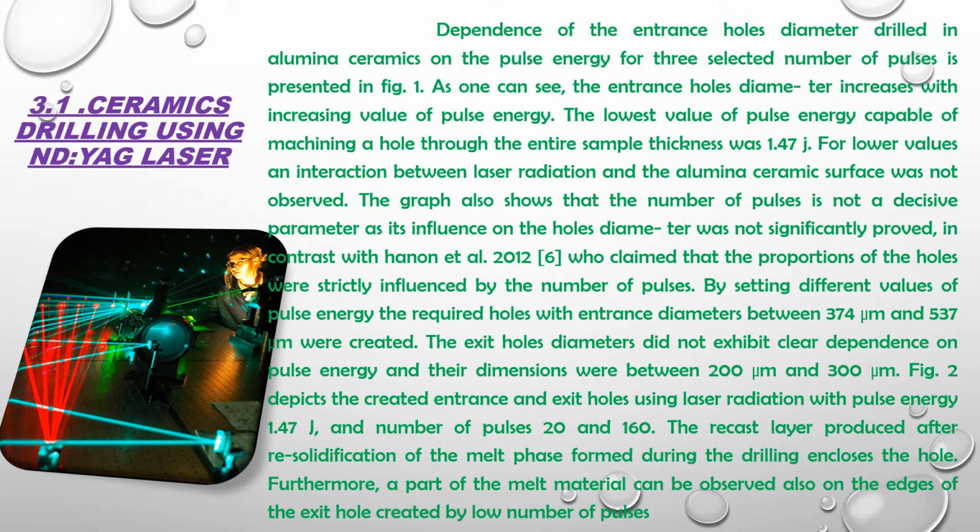Ceramic drilling using Nd-YAG laser. The dependence of the entrance hole diameter drilled in alumina ceramics on the pulse energy for three selected numbers of pulses is presented in figure 1. As one can see, the entrance hole diameter increases with the increasing value of pulse energy.